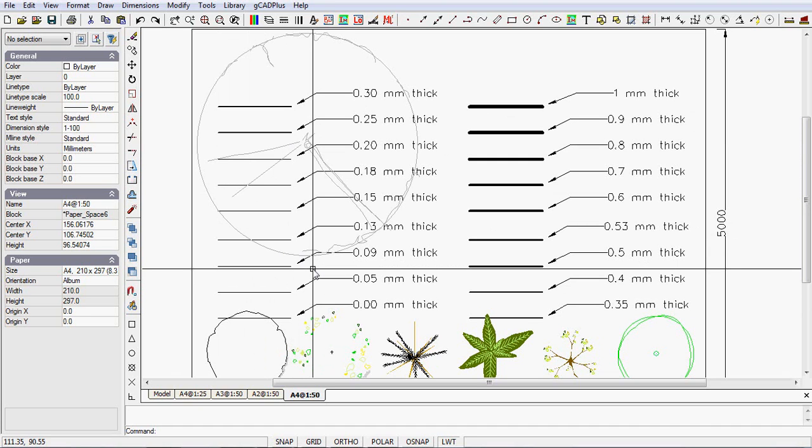I should have started by saying you want to accentuate, say, the house footprint. You might want a lighter line for boundaries. You might want a slightly lighter line for irrigation lines. You might want a heavier one for any screening that you're doing, any half-wall screening, say in the garden area, might need a different thickness. Well-constructed drawings, when they use different line thicknesses, certainly stand out as highly professional. So that's 1:50 on an A4 sheet.